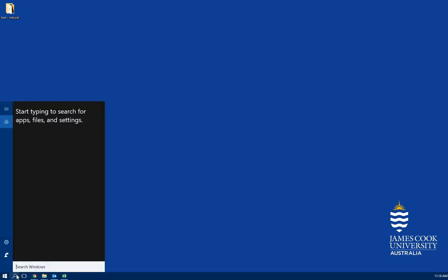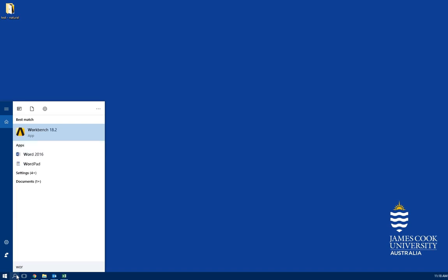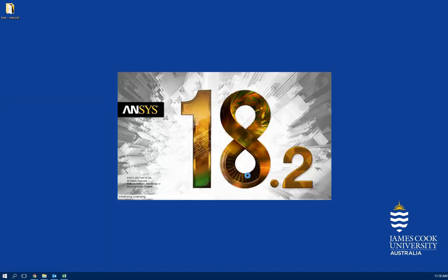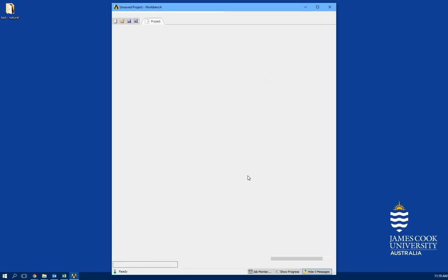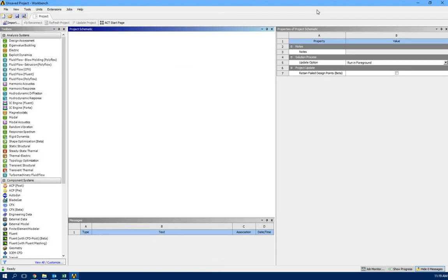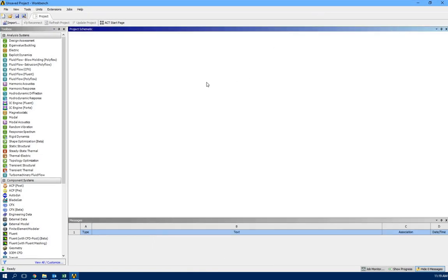This is going to be one of the procedures or steps you're supposed to do for any simulations. So you can't report any simulation without doing mesh dependency test. For this simulation, I'm going to make everything simpler. It is going to be 2D case for a 90-degree bended pipe, and it is going to be steady state. So no time dependency, we're just going to focus on mesh size.